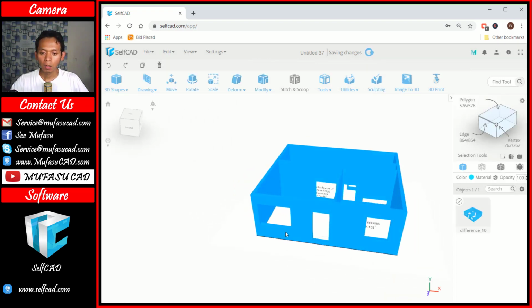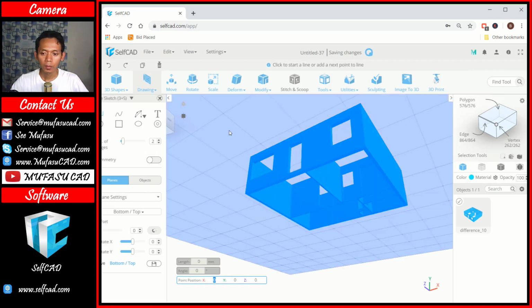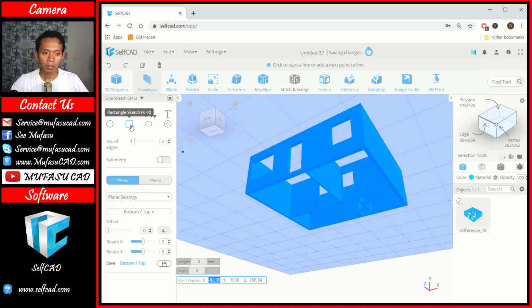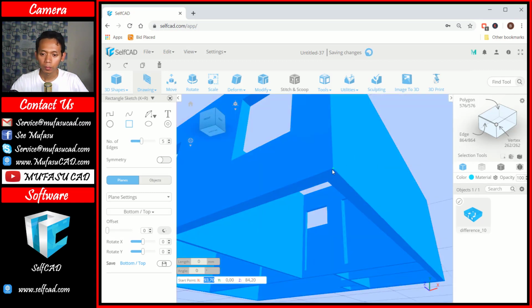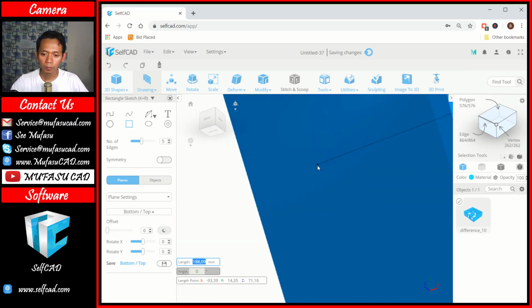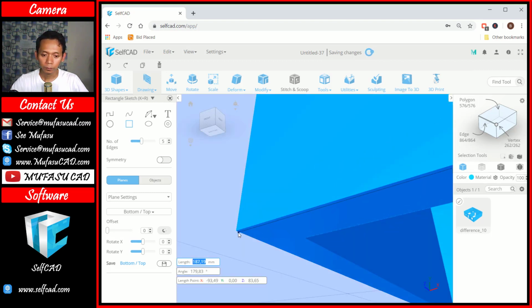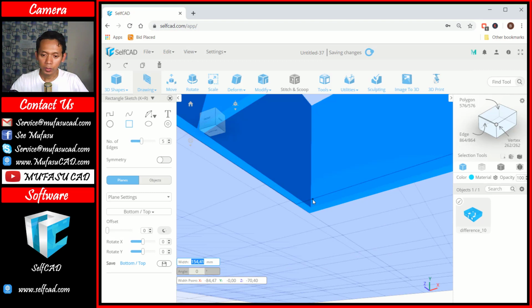Now for the base, I will use 3D Sketch. You can click here 3D Sketch, and we can use this rectangle sketch. Okay, we can create a rectangle. Start from this point. Okay, I will move into this point. Next, we can move into this point.